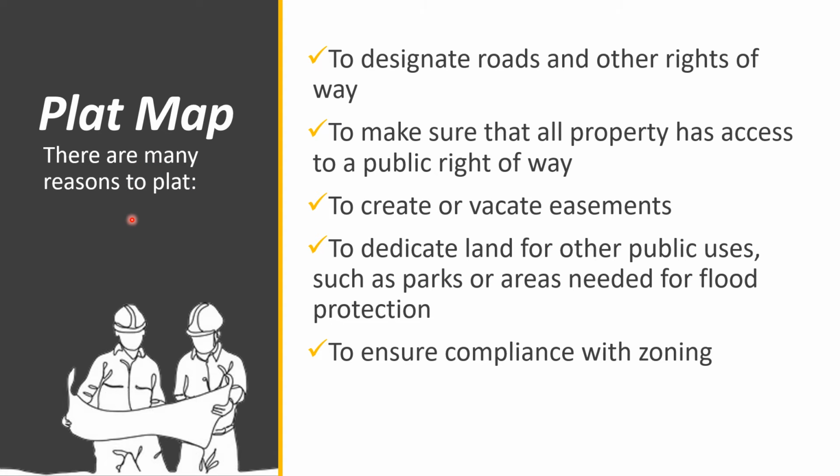plat map. So there are many reasons to plat. So that is to designate roads and other rights of way, to make sure that all property has access to public right of way, to create or vacate easements, to dedicate land for other public uses such as parks or areas needed for flood protection, and to ensure compliance with the zoning.